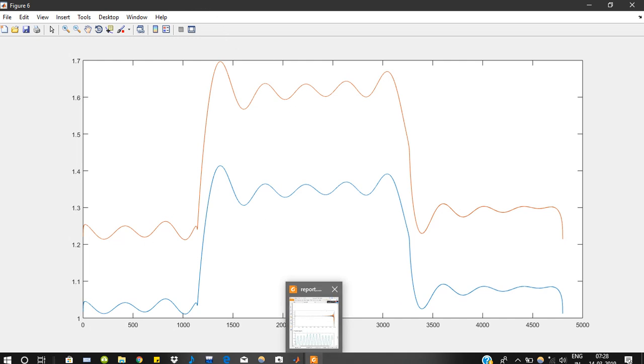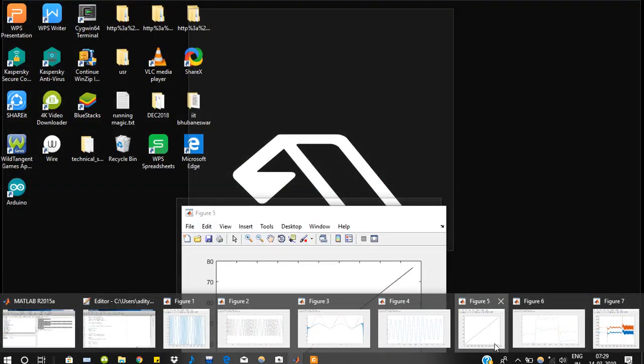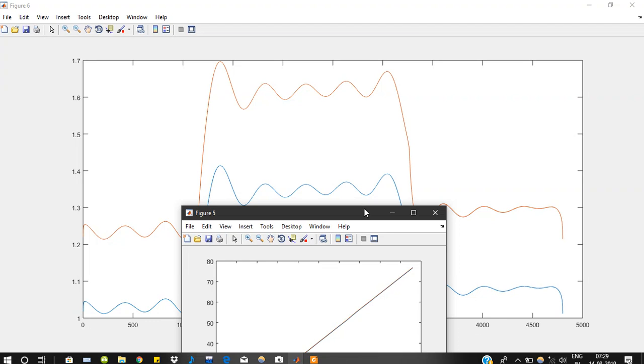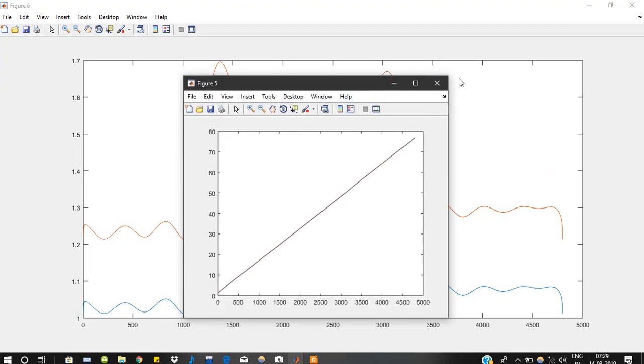If you look at the phase response, you see the phase response is linear. This is quite expected, as the frequency of the signal is constant, so your phase is going to be nothing but omega t itself, or something that is linearly dependent upon time. The slope of this curve, if you estimate it, is going to be your frequency itself.